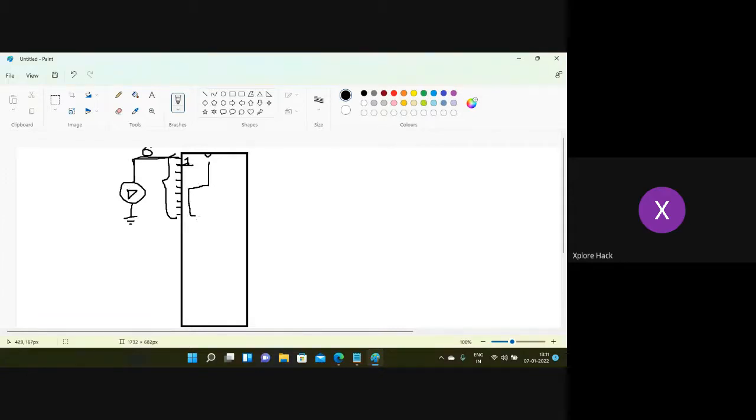To create a clock pulse, you can use a specific hardware circuit called a crystal oscillator. This crystal oscillator can produce the clock pulse to make the microcontroller work. The strength of the crystal oscillator which we are using in PIC is 20 megahertz. The unit of clock pulse is megahertz.